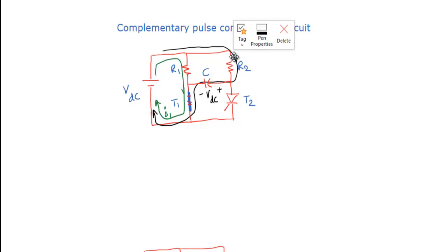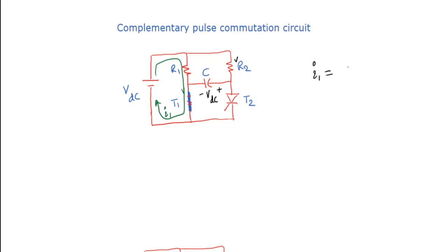Once this current disappears, then this charging current won't be there. In that case you will have only the source current flowing through the resistor R1. That means this is disconnected, this circuit will not be there. Okay, so that's what will happen. In this case you will see that only I1, that I1 is nothing but VDC by R1 only. So that's what happened.